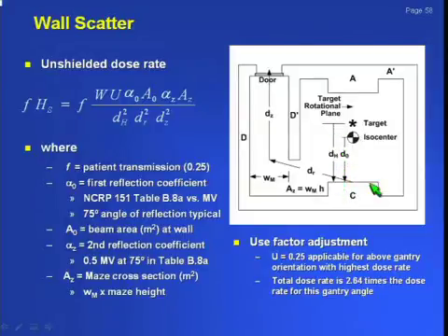You need to know the width of this barrier, the width here, all of your wall dimensions in 3 dimensions go into your calculations. So you want the distance from the target to the surface of the barrier, from the center of that barrier to the center of your maze, and then from the center of your maze to the center of your door at 1 foot beyond the door. Those are your significant distances that you use to do a maze calculation for wall scatter.